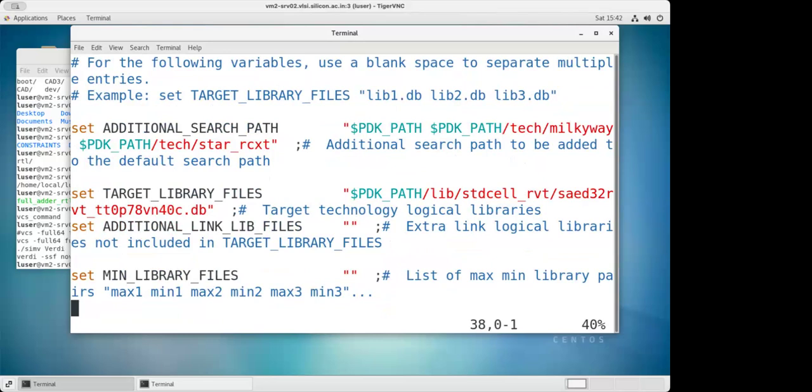Again, these variables you can define in the main file also, but industry people prefer commands in one file, all the variables in one file, and the relationship between the command and the variable in a third file. So that's the reason they have common setup and DC setup. Common setup is common for all the tools. DC setup is only for the DC tool. And then run DC, run placement, run ICC, whatever there is, is where you have to run all these commands.